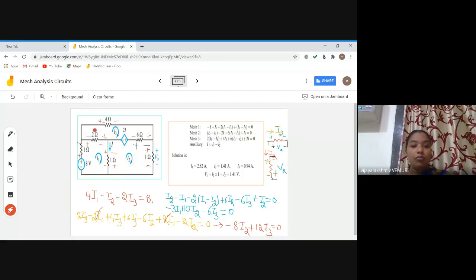Now coming to the third loop, when I start here, I3 has entered the 4 ohm resistor, and entered the 6 ohm resistor in this direction for this loop. So I have given plus for 6 ohms in this loop as plus here and minus here. Now go like this. Okay, this is plus here and minus here. So this is how I have given the sign conventions.